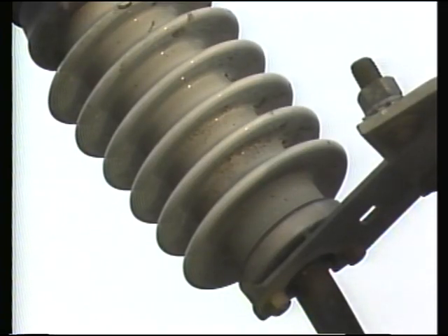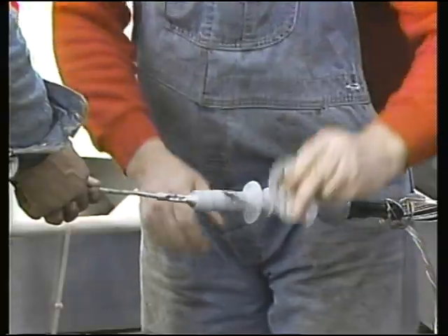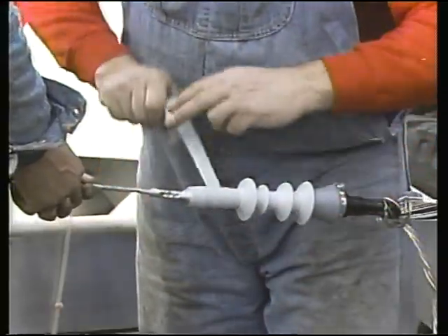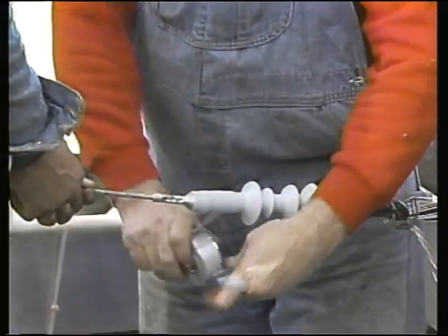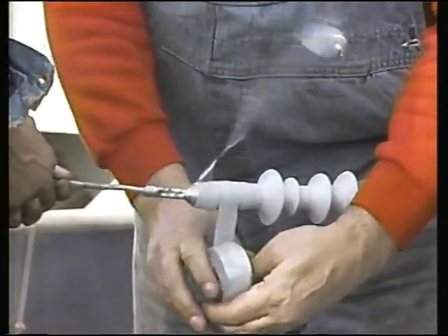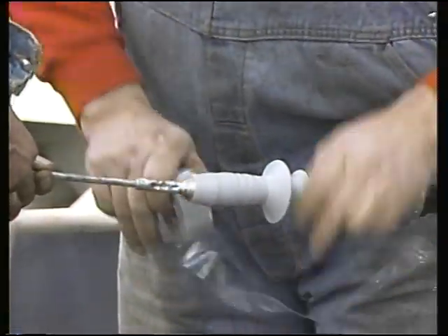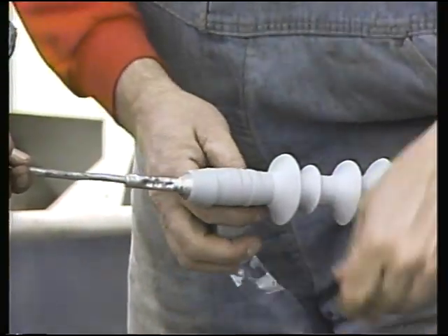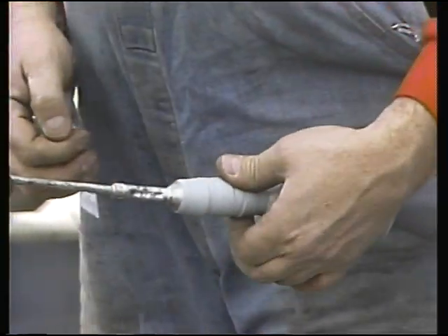Tracking can result from a combination of voltage on the conductor, contamination such as dirt on the outer layer of the termination, and moisture. Sometimes it's necessary to seal a termination to protect it from water and other external contaminants. When this is necessary, a Class 1 termination is used. Also, Class 1 terminations can provide a means of maintaining pressure in a cable if it normally operates under pressure.